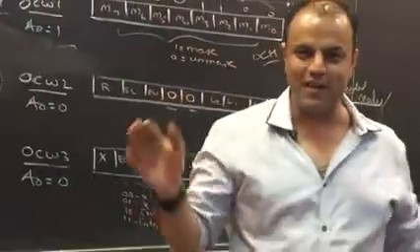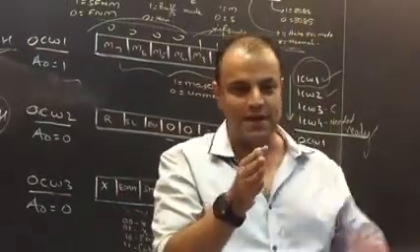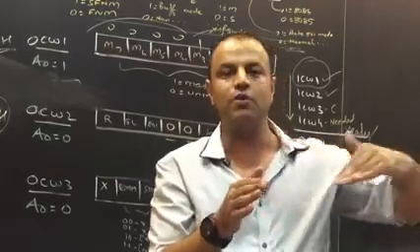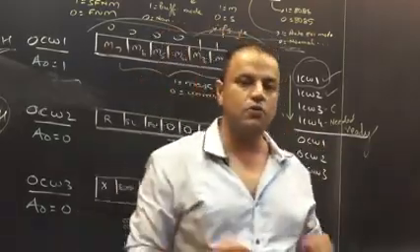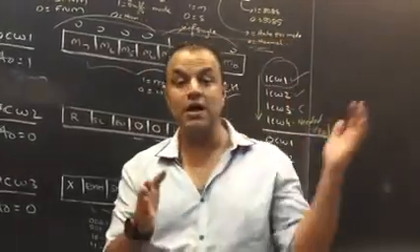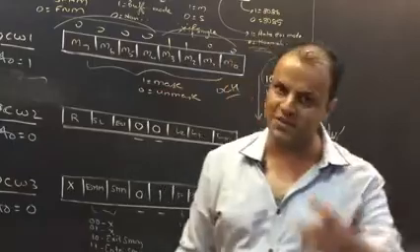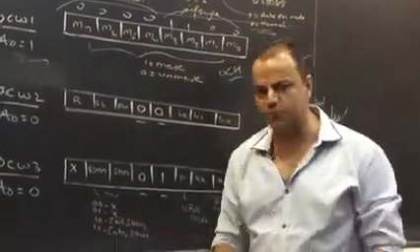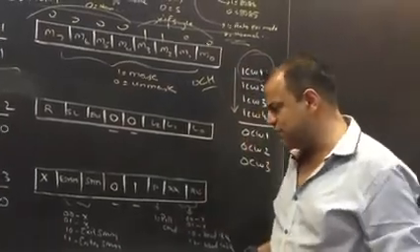If you get an interrupt of IR3, you are in the ISR of IR3. During that, IR 0, 1, 2 will be serviced. IR 4, 5, 6, 7 will be serviced. The only one not to be serviced will be IR3. So this is a mode used where you don't want priority. Anybody can interrupt anybody except for the same interrupt. Since you are specially masking the current interrupt, it's called special mask mode. I have explained to you what is special mask mode. This is how you enter and exit special mask mode. Are you clear? Again, as a student, you'll never do it.